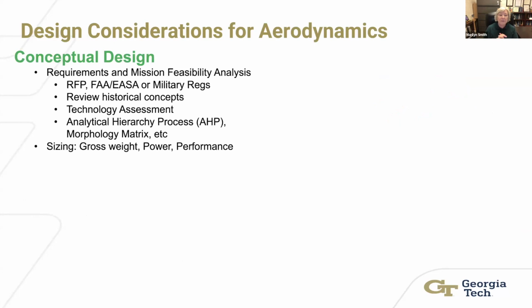Now, let's talk first about design considerations for aerodynamics. First is conceptual design. That's what you're doing now. Requirements and mission feasibility analysis is your goal here. Look at the RFP. Look also at requirements from either the FAA or EASA or the military regs. Okay, you have to look. Now, the guiding principle is what GoAERO put out, but look at these other things too, because if you're serious about taking GoAERO beyond just the prize money and making it a viable design, those other things you need to look at as well.